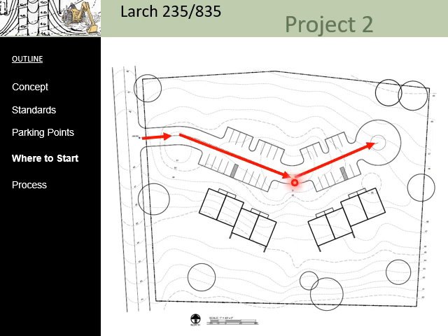But you know that for a parking lot, the closer you can get to a 2% slope, the easier it's going to be for people to drive on it. You cannot go less than a 2% slope unless you have slope going sideways that will allow it to drain. But you're going to start with a target of trying to get somewhere around a 2% slope, and you definitely do not want to go above 5% if you can avoid it.